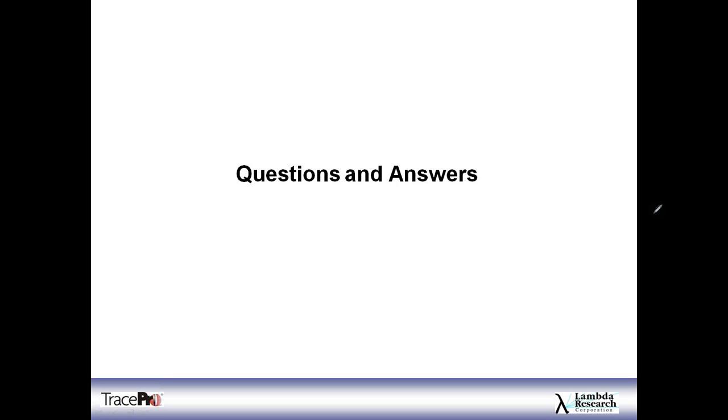Good. The next question is, what is the benefit of having this BSDF data to the radiance or luminance analysis? Are we getting a closer, real world result? Yes, well, that goes back to one of the slides I mentioned, where in a perfect world, at least for those of us doing modeling, everything would be perfectly specular or perfectly diffusing. But really, reality of the real world is somewhere in between. So this allows you to add the scattering properties that your models or that your objects really have.